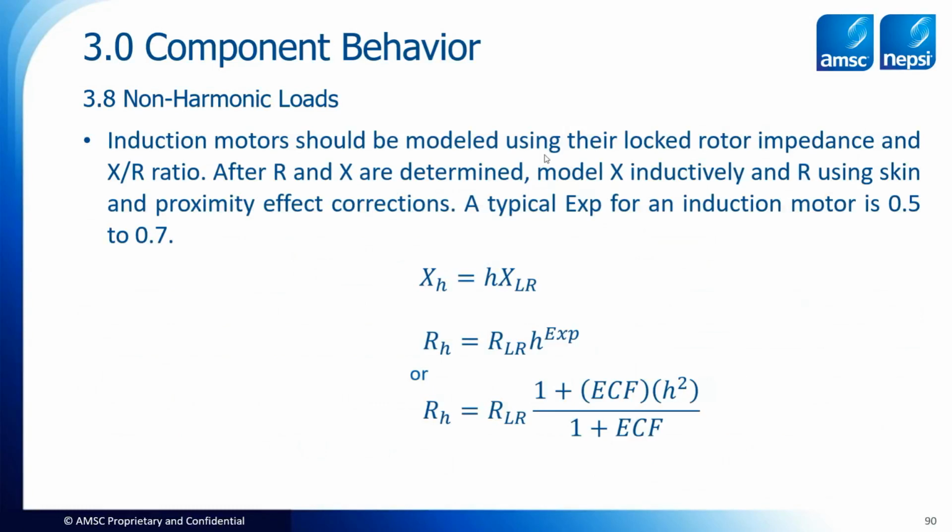So now let's shift to induction motors. How would we model an induction motor? The accepted practice is to take the locked rotor impedance with an X over R ratio, break it up into R and X at the locked rotor condition, and then for the X value, choose the harmonic number, just like we did for anything that's inductive: harmonic number times the locked rotor reactance. And the resistance, of course, using one of these types of skin and proximity effect simulations. I found that EXP for an induction motor is typically between 0.5 and 0.7.